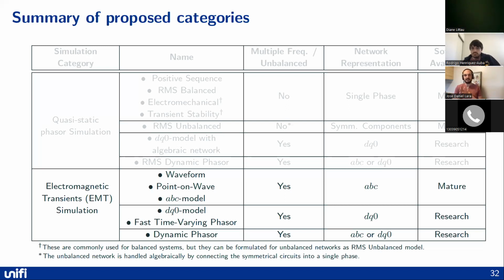So, that's a strong conclusion for us, because we basically are trying to say, if we start wanting to study IBRs and systems with a lot of renewable resources that are grid forming, and we're finding out that the boundary limitations and the effects of the simplification of small signal perturbation theory give results that are not necessarily stable, the application of a dynamic DQ0 model could be a solution to that kind of thing.